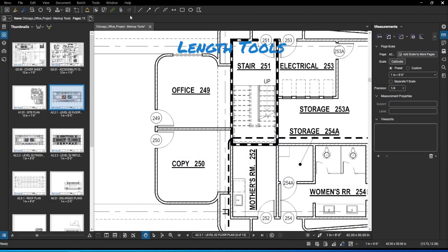The Link tool is the most basic tool when working with measurement tools. Before you begin taking measurements, you must ensure that you know the proper scale and that your document is properly calibrated to that scale. If the calibration is off, your measurement will not be accurate. Calibration allows Revu to determine a PDF scale, enabling accurate measurements. Revu can calibrate a PDF to a single scale or to separate X and Y scales as needed.